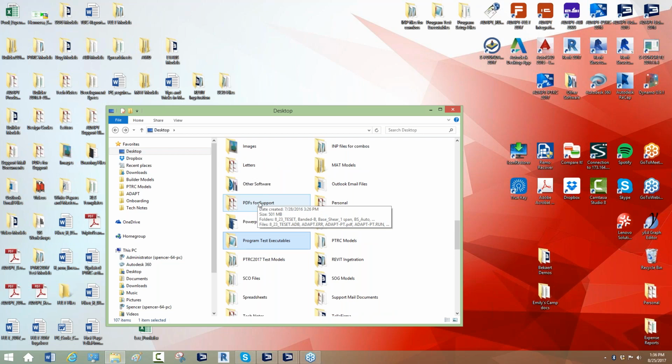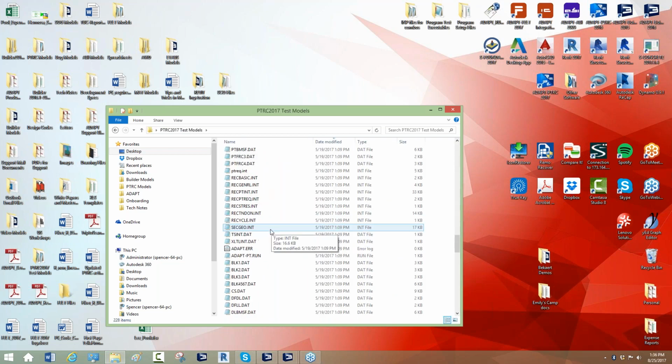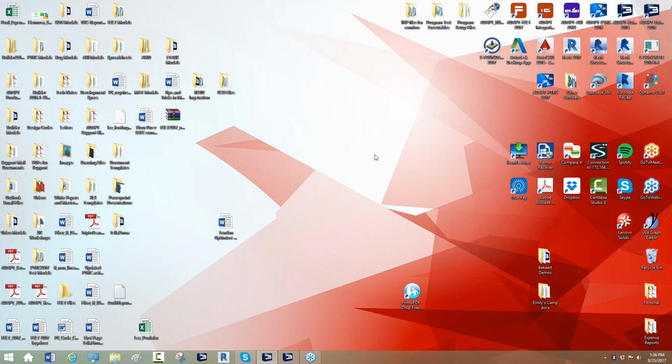Yeah, I actually have a version of the software which creates files. So Ted, I'll show you off the webinar what I'm referring to. But ultimately, we have a version of the program which has a load generator, a load combination generator. You put in your loads, and the program will produce the load combinations based on the design code that you have selected.